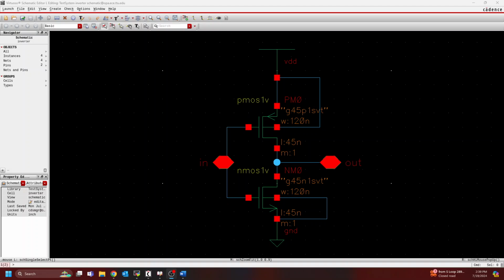Now for this video, we're going to extend an existing schematic that we've already made into something that can actually be fabricated on chip. So we're going to extend this schematic into a layout. Unfortunately, if you just try to send schematic files to a foundry or a fabricator, they would pretty much laugh you out of the room, because you have to show them how you want the physical transistors laid out, how you want them interconnected, what layers you want them connected on, and things like that.